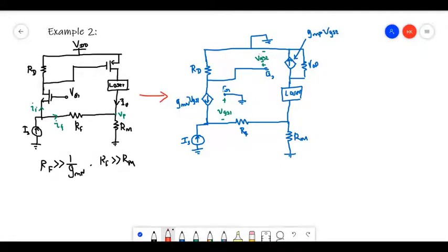So it is grounded here, and this is actually the N MOSFET, right? Here at the gate, this transistor is given a DC voltage. So in the small signal model, it is grounded, right? And this is that current source going from drain to source, which is GMN times VGS1. This is G, this is the source, so the VGS1 voltage is this one.